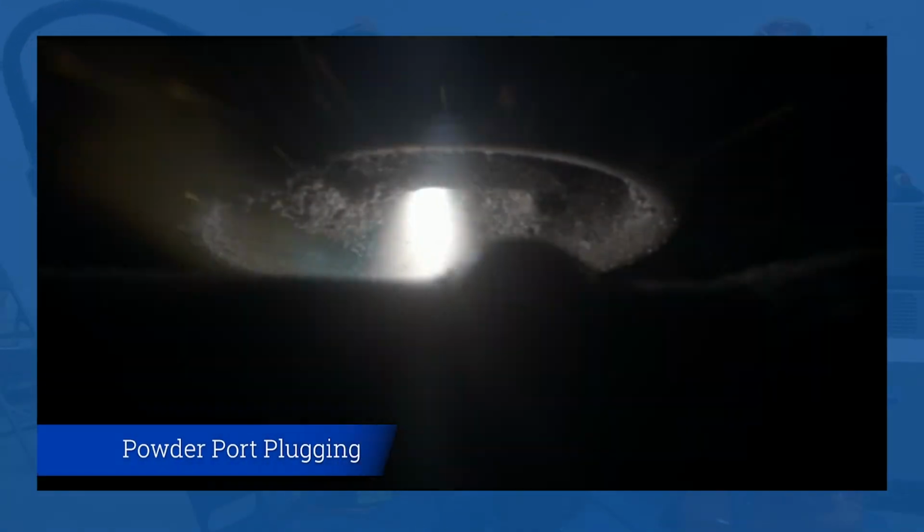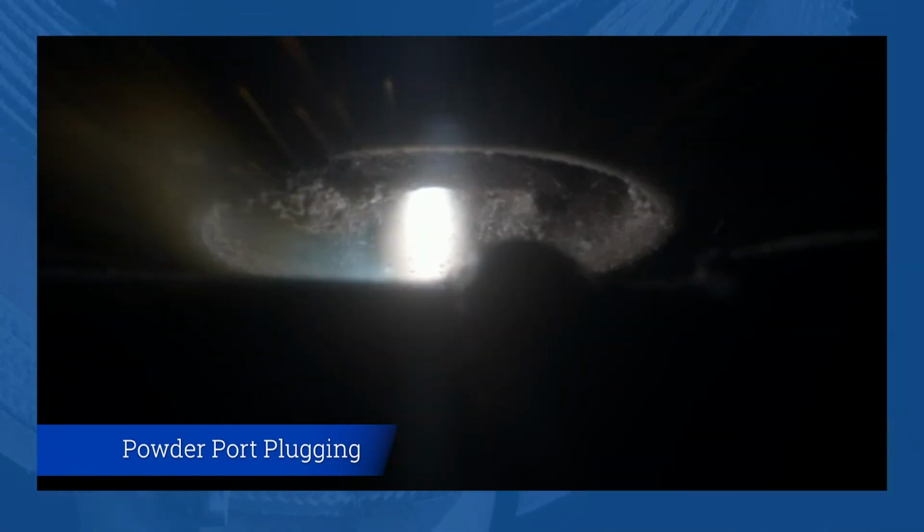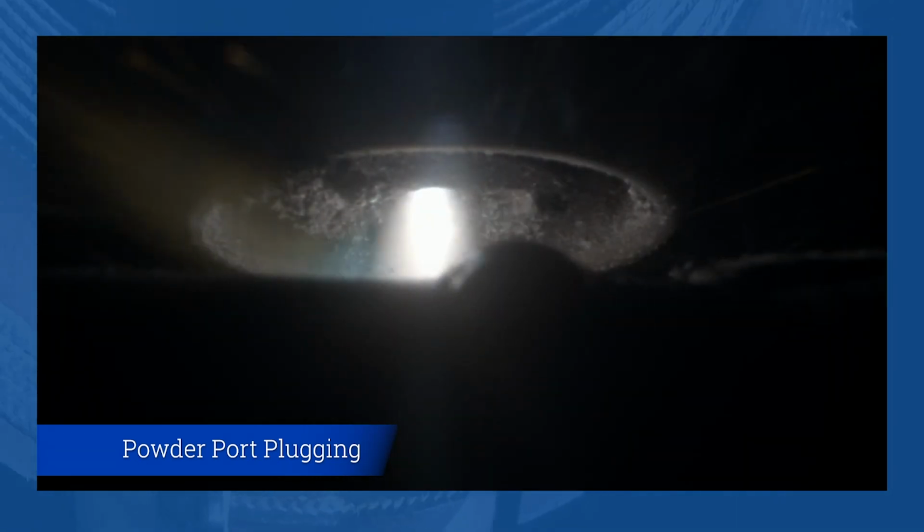Now we have some bonus footage for you. One problem which is unique to powder welding with plasma is port plugging. I showed you the end of the torch. There's two small ports. That's where the powder comes out, enters the plasma column, and goes to your part.